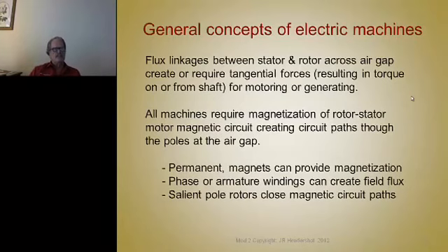I think if you look at the air gap stress in electrical machines, we're going to study that later, but the highest ones that I've ever seen put out 35 pounds per square inch of air gap stress. The ones in your house, the motors that are used in your refrigerators and your washer and dryer and your household appliances, they're in the 1 to 2 psi air gap stress requirements. And what that is, a force is created in the air gap times the radius of the air gap is the torque on the shaft.